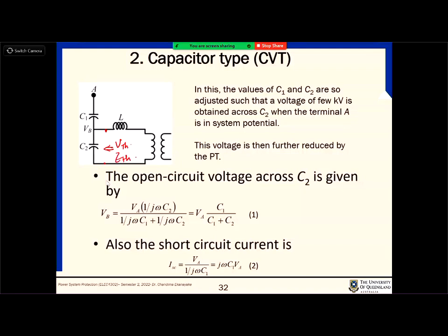How do we develop the Thevenin equivalent? You remove the load side and then look at the source circuit here. So if you remove that, then across this, B and C, right? A, B and C. So across these two points I need to find VTH and ZTH.